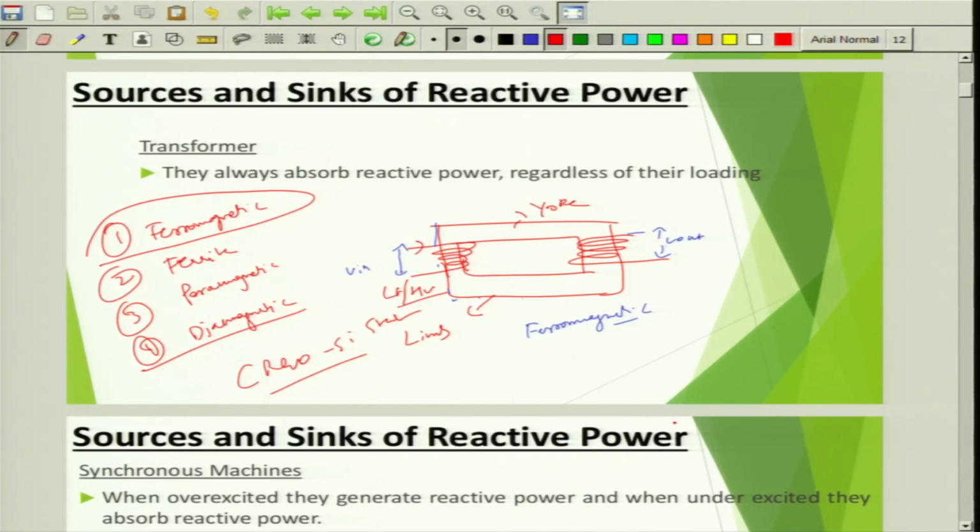So what happens, there is some current which is flowing through the primary winding, and because of which there is MMF which is being produced. MMF is called magnetomotive force. This is nothing but number of windings times current, that's it. There are some number of windings wound across this limb, and a finite current which is being pulled, because of which there is a magnetomotive force present. Now like EMF, it's equivalent to EMF in the magnetic circuit.